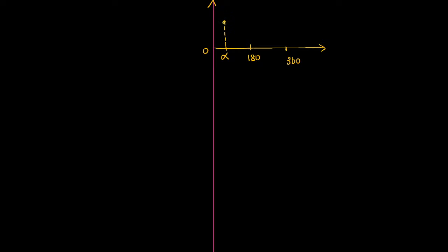For your understanding I am keeping a fixed general value. So this is the waveform pattern that we have observed for the output current. Yes or no? Yes sir, this is the waveform that we observed for the output current. From 180 to 360 the current is 0 ampere. From 0 to alpha also the current will be 0. In the remaining portion, the current flowing through the circuit can be defined as Im sin omega t.